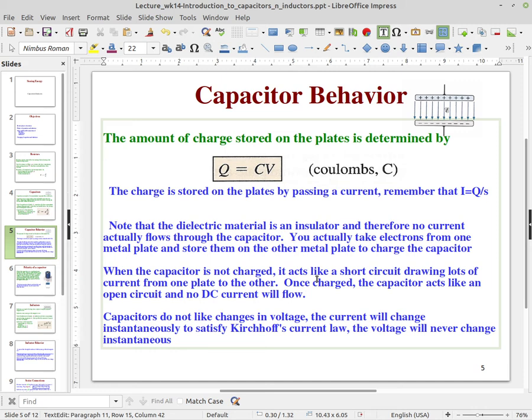And when you look at the old CRT type TVs and things, they would have very large capacitors in them that could have charge on them. Power supplies are the same way. Power supplies will have a large capacitor, and so when you're working on a power supply, you have to be very careful. You want to make sure you discharge all the capacitors before actually doing any kind of work disconnecting them, or you could get a very serious injury and shock.